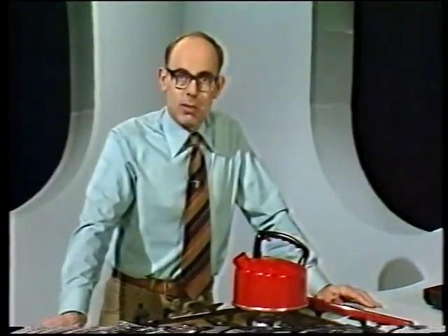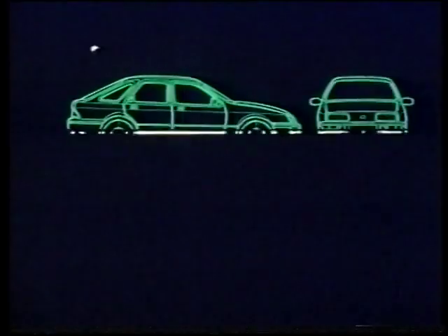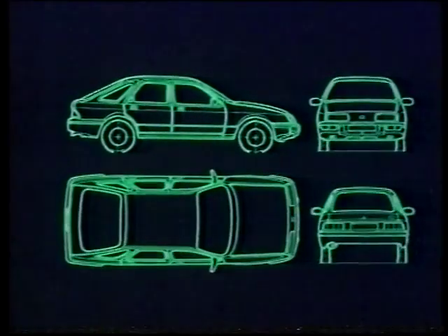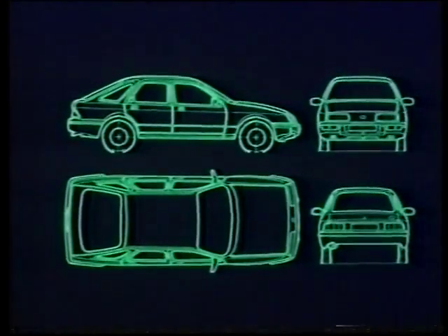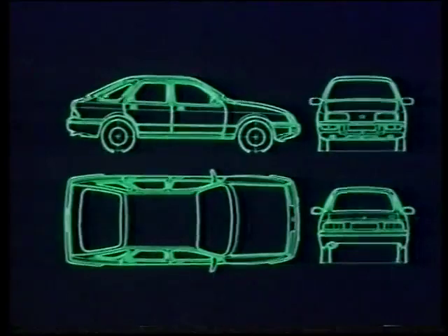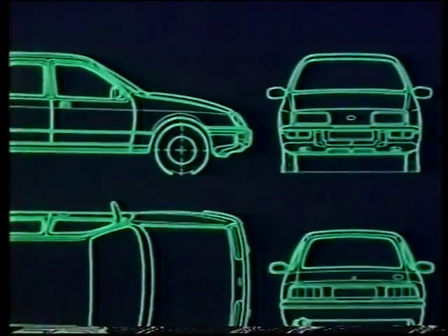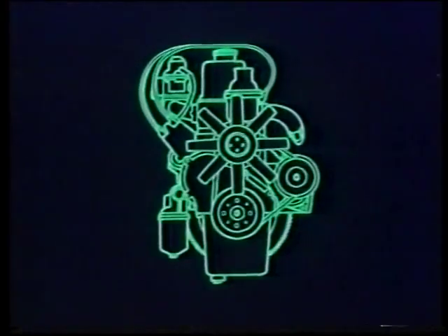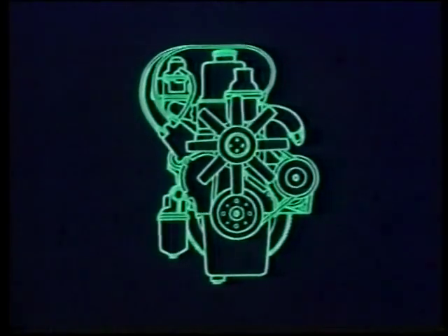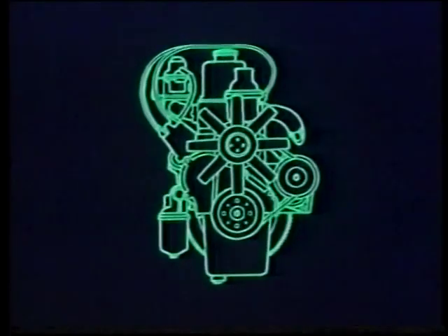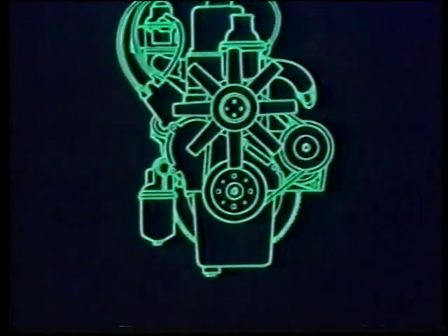Well, that's okay for a house, but what about a car? To describe the overall performance, we could define the system boundary as an envelope which encloses the whole car. On the other hand, if we were interested in the work that could be derived from the engine, then maybe we should define a system to enclose only the engine. A more useful and simpler starting point, however, might be to consider not the performance of the whole engine, but to examine the performance of a single cylinder, and a system would then be defined to enclose only the gas in the cylinder.